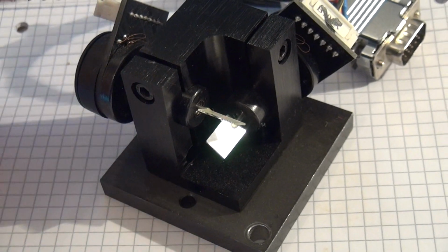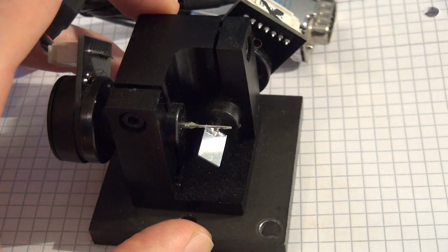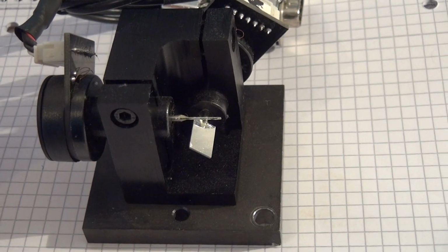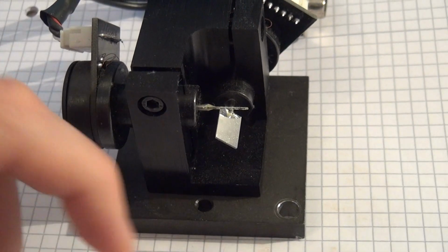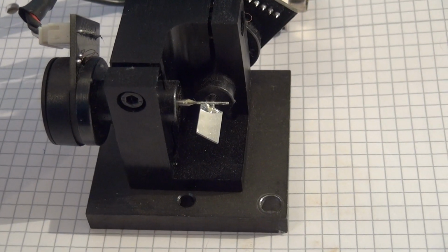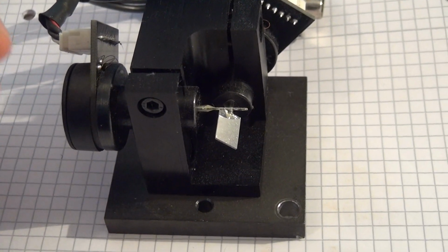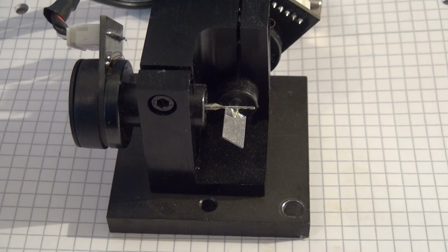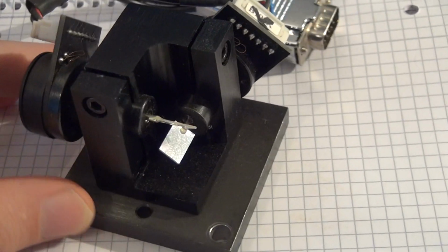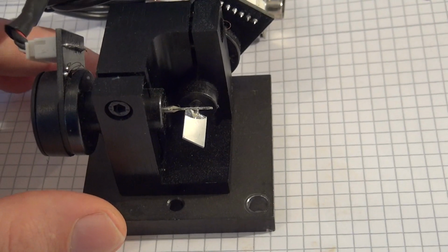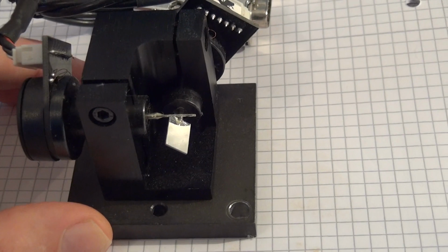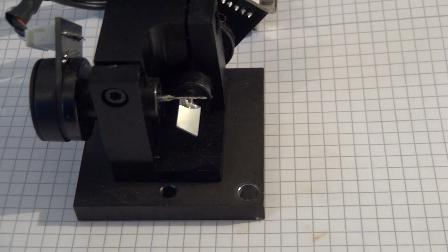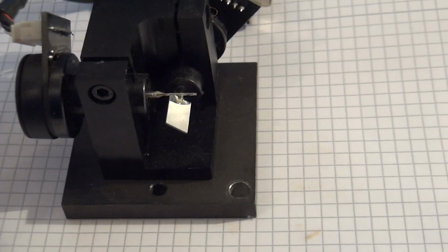So I guess you are already all familiar with this. This is a scanner I pulled from a laser projector, and it simply consists of two mirrors and two motors. The motors are called in this case galvanometers. Essentially they are motors that consist of a permanent magnet in the middle and a coil around, and they have a feedback system at the back, so the controller knows where the mirror currently is and can control it very precisely. Technically this is a second order dynamic system, and the way the laser beam is deflected is it comes from here, then the lower mirror would display your x-axis, the upper mirror would then generate your y-axis, so that's the y deflection then.